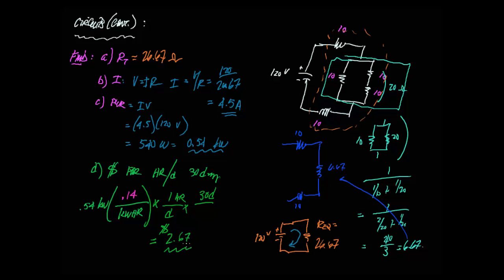Again, that's only half a kilowatt or 500 watts, not only, but it's not a ton. It's not like there's a lot of things plugged in there or that it draws a lot of power. So real good example for a potential exam, hint hint. And if you understand that, you're understanding series and parallel and calculating total current and power and cost. And also throw in here, if we had to put a fuse value in there, as long as the fuse value was greater than this 4.5, we are good. We won't blow the circuit.